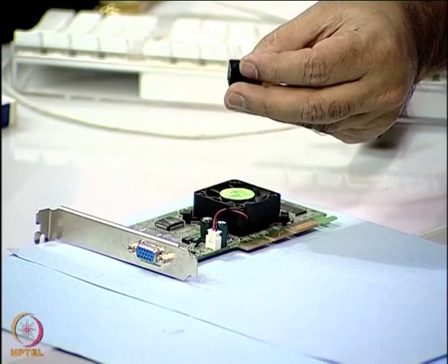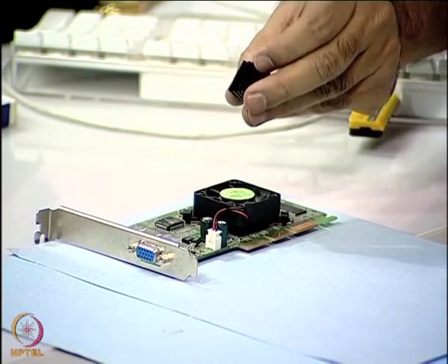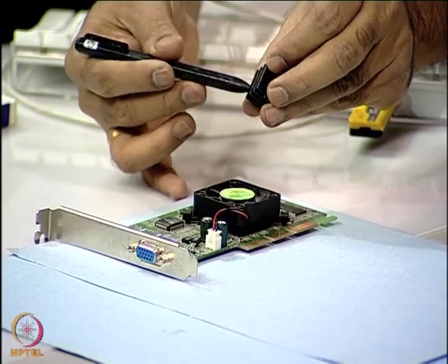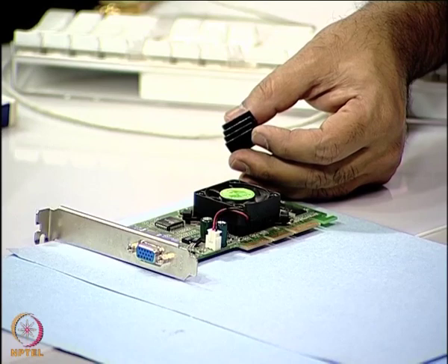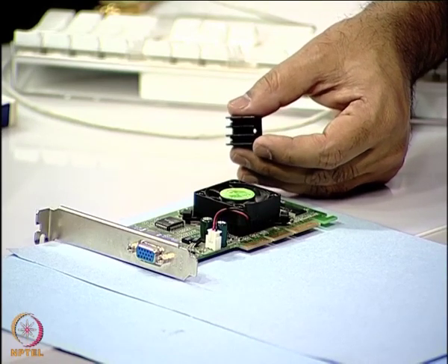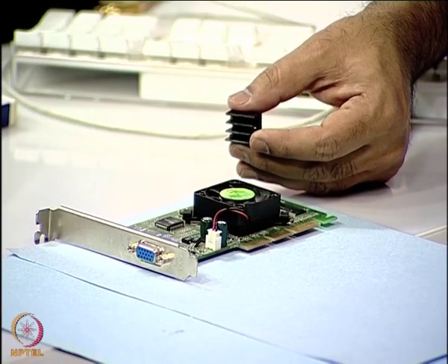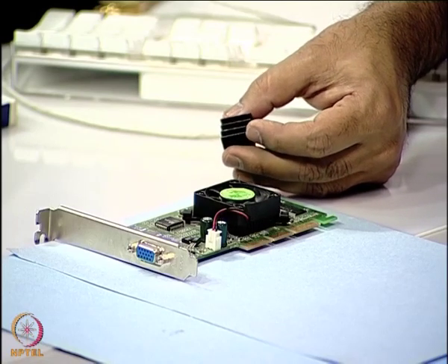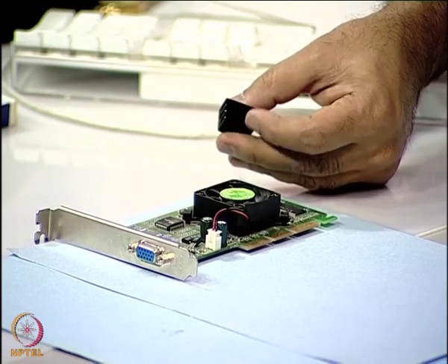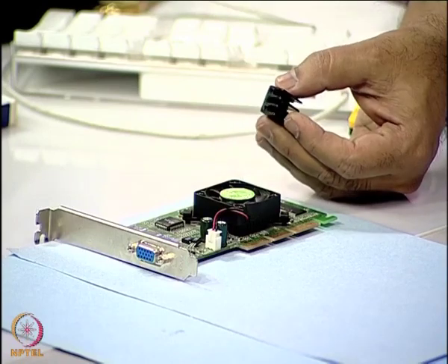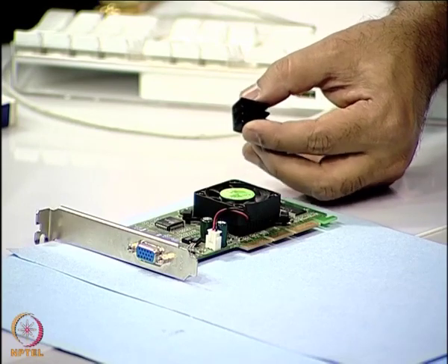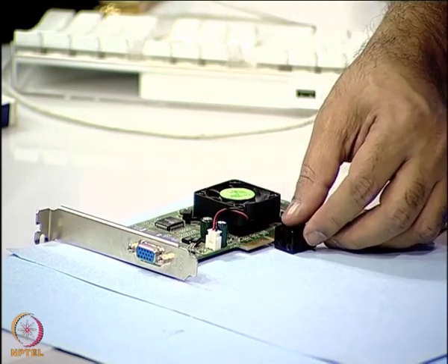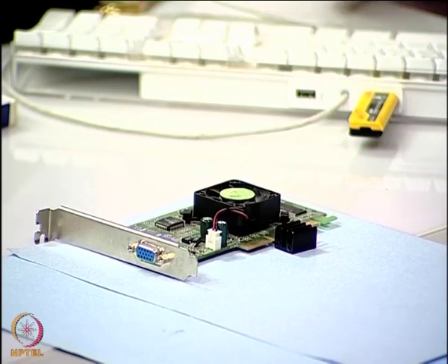and you can see this is lightweight and this is coated black, okay, and you can see the special corrugated structures here, and these structures are provided basically to provide more surface area, and more surface area means more heat can be removed from the active device. And for effective cooling, this is coated, this is black anodized aluminum. Okay. So, these are an entire set of technologies that are available today, which a designer should be aware of.